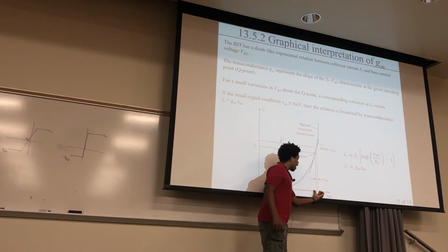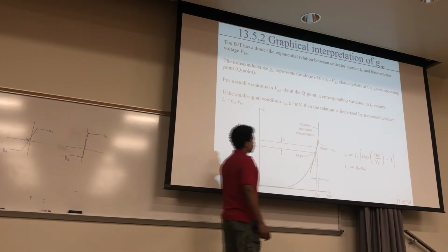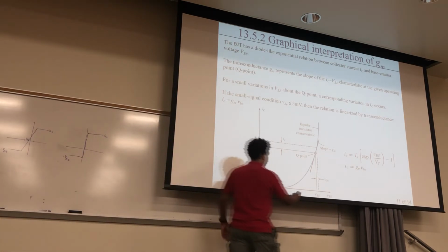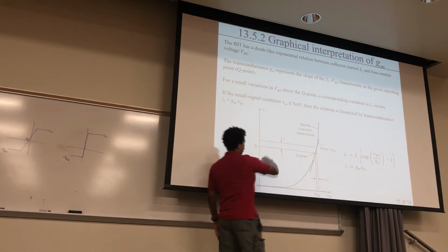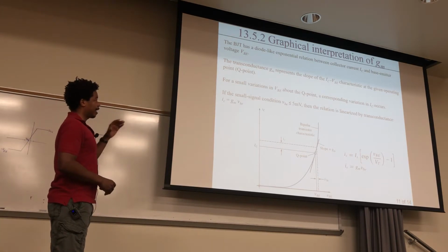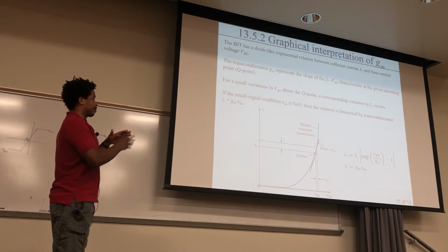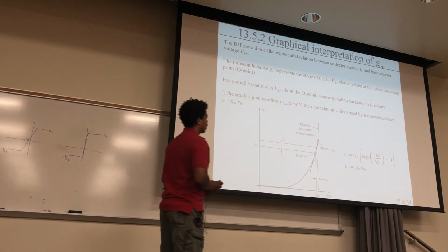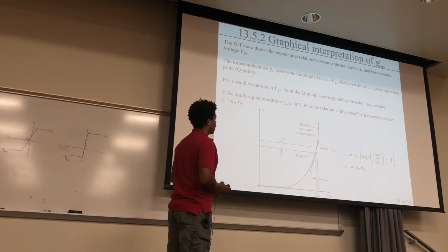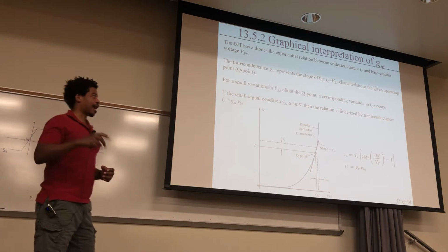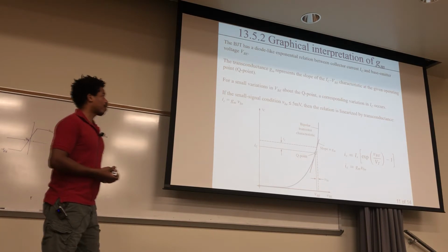If it's larger than that, you'll have some distortion. For example, if you put in a nice pure sine wave, it won't come out nice and pure. It'll be slightly distorted, and may experience some cutoff or a little bit of morphing. But based on what we know about Fourier series, you can represent that with just some higher order harmonics.